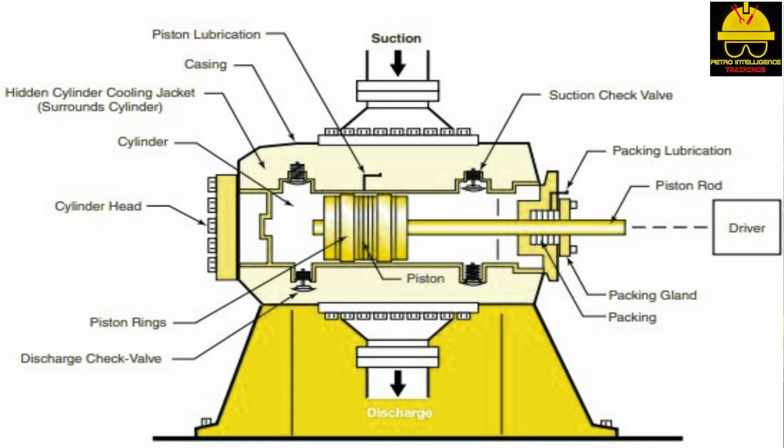During operation, reciprocating compressors perform best with clean gases. Entrained water, dirt, and impurities will cause excessive wear on the piston and cylinder. Reciprocating compressors are selected when low flow rates and high discharge pressures are required. There are several advantages of using a reciprocating piston compressor. They have a flexible pressure range and overall capacity, low power cost, and high efficiency rating. They can handle density and gas composition changes and small volumes and can deliver high pressures.